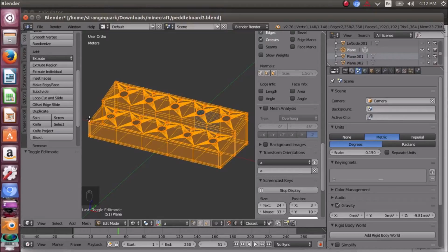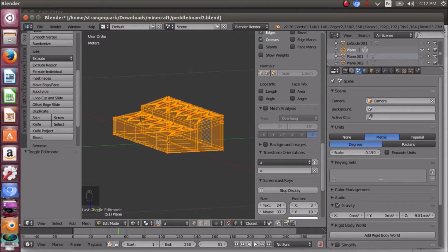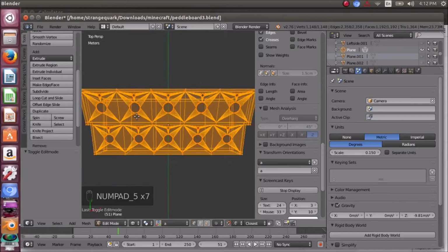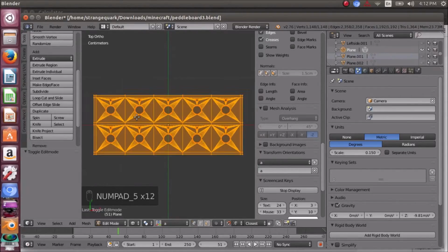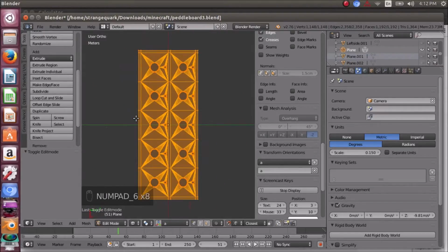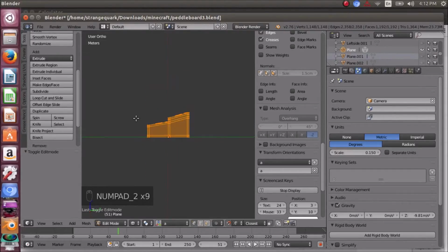But in any event, I want to separate this mesh into separate component objects. The first thing is that it may be easier to work in orthographic view when you're doing this type of work. So you hit numpad 5 and that'll switch your view so that we have a top-down flattened image. And secondly, we'll start working on the component division here.